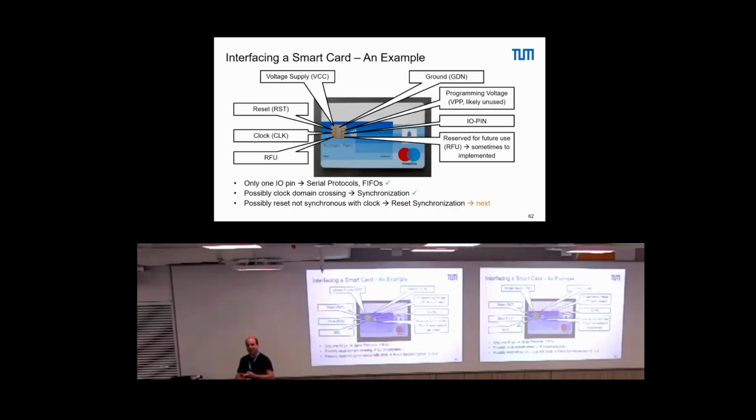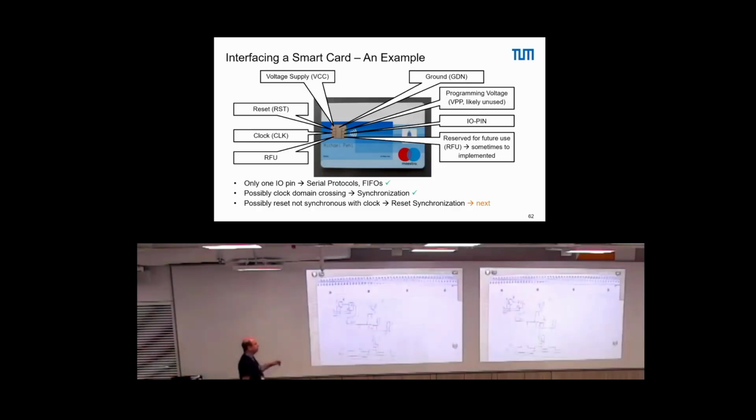What I try to ask is, why is the clock the reason for that? So we had this construction here on Friday, and we neglect this part. Now we do all the reset only synchronous, pure synchronous. The input here is not synchronous. Do we avoid the inconsistent state here?